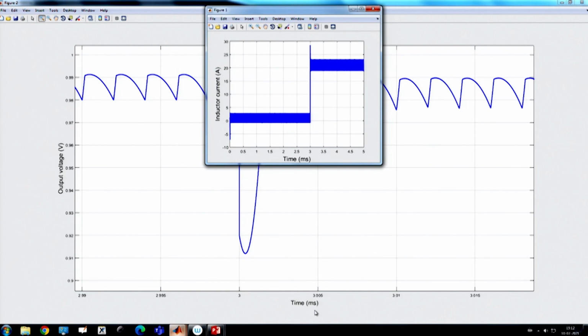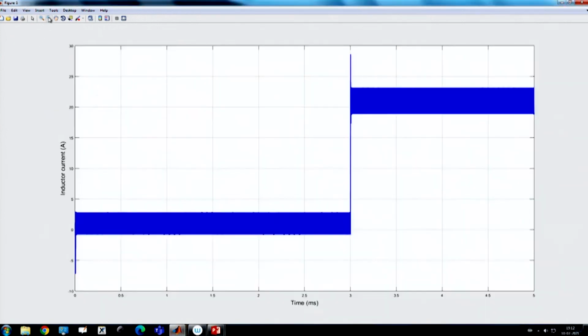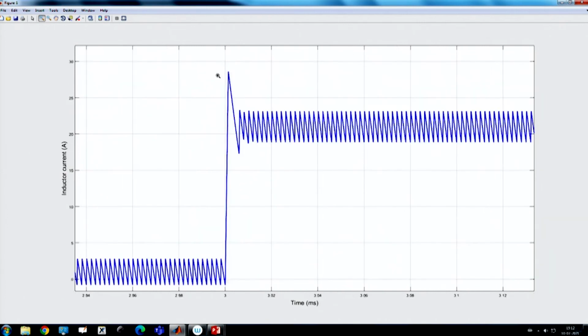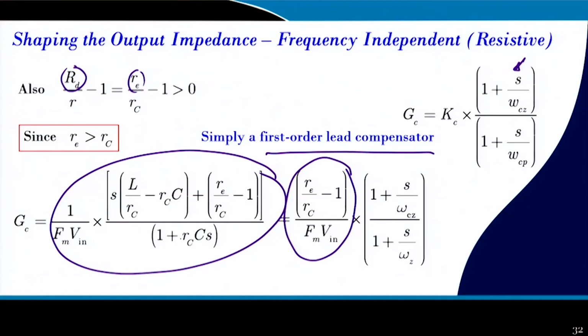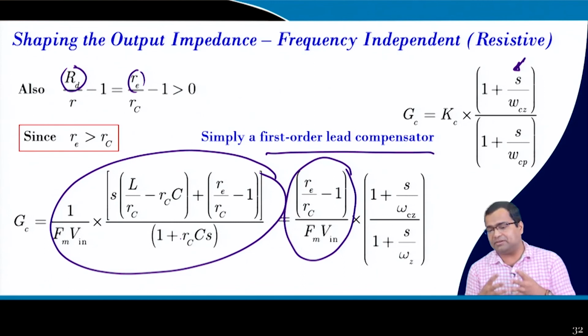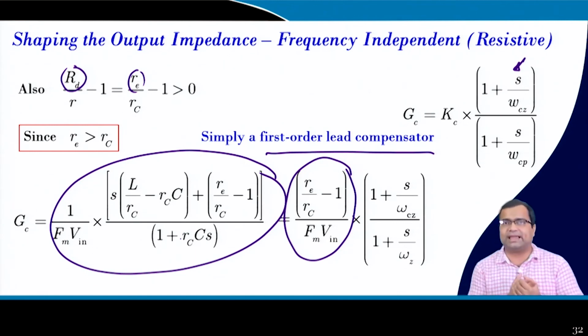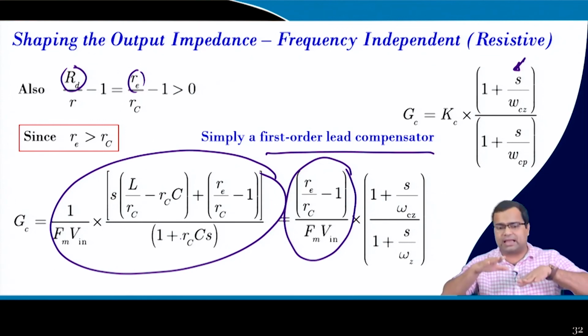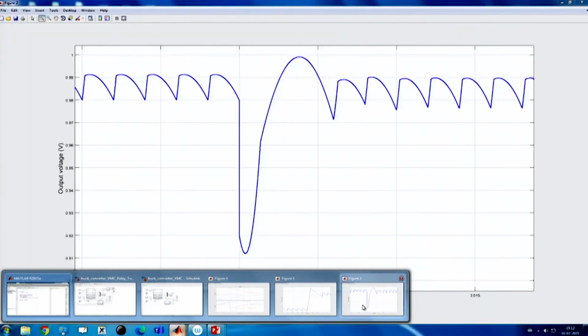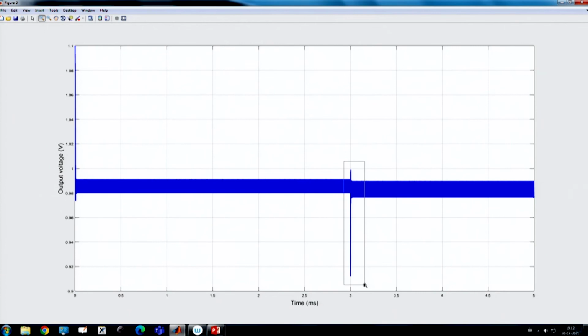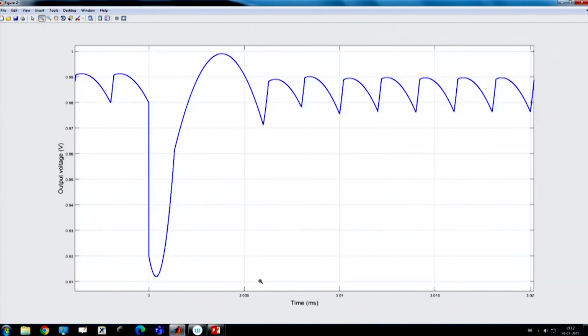And if you see the inductor current waveform, it looks like an extremely fast, very fast transient response. Which means the lag lead compensator will be a very suitable choice from the load transient point of view, but you may not get 0 steady state error, but by increasing the gain you can reduce the steady state error. It can almost behave like an immediate response to the transient, and that we got from the response, it almost responds immediately, maybe a 1 cycle or so, because of the finite slew rate of the inductor and capacitor.